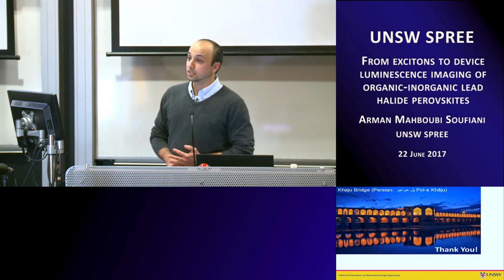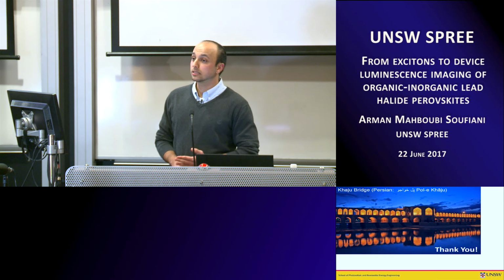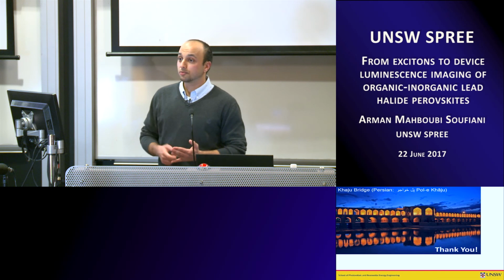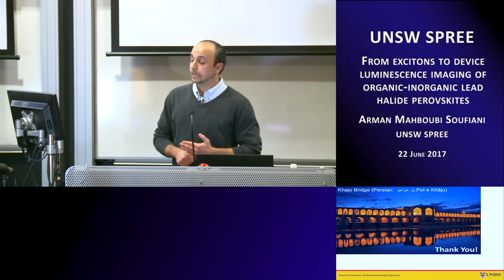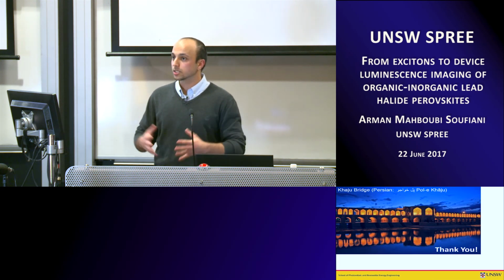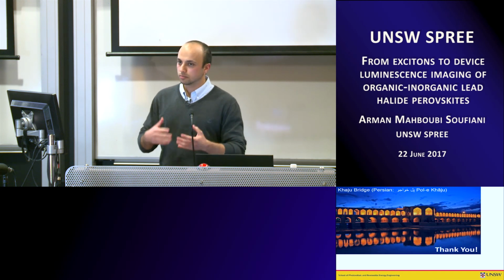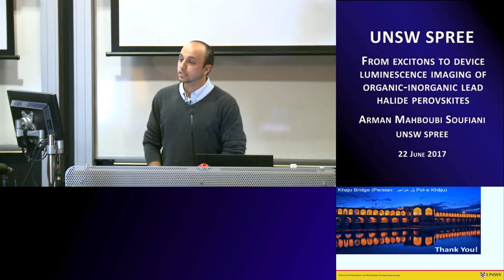Firstly, proper encapsulation can improve the stability of these devices. One of the reasons of degradation is the interaction of the light and oxygen in the perovskite layer. And proper encapsulation prevents the oxygen from going through. So you think oxygen diffuses into your structure? Can be, because our technique is one of the very simple techniques for encapsulation, which is epoxy edge sealed. My colleague here has developed a technique which is much better than this. So if the encapsulation technique is improved, you probably can get more stable devices.